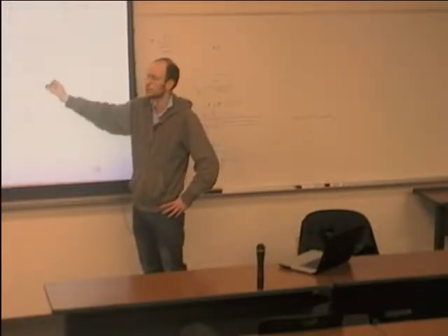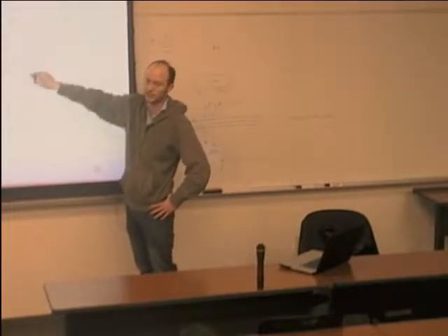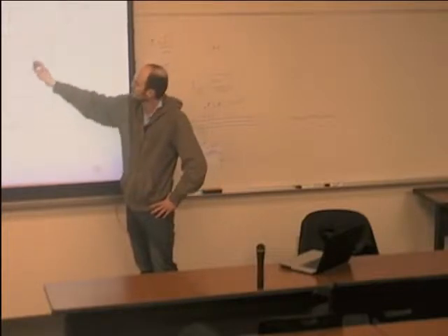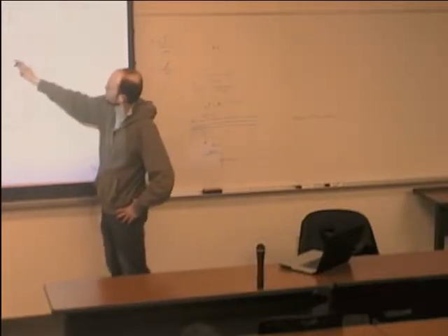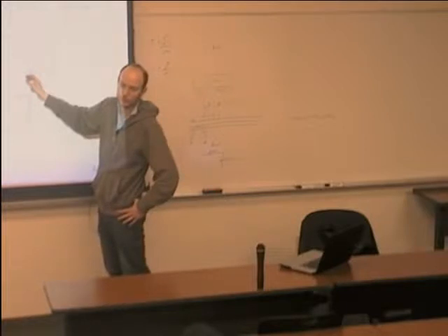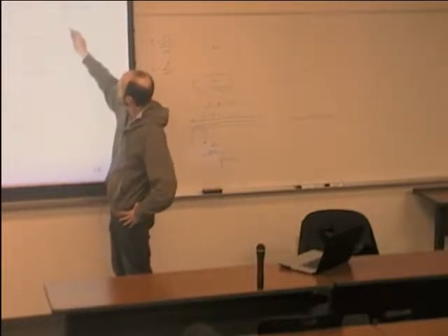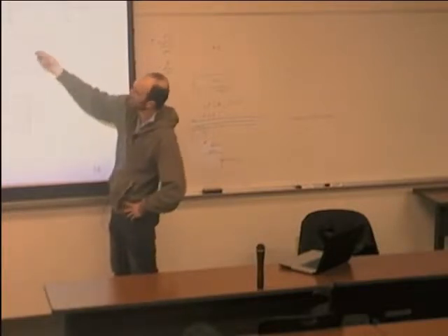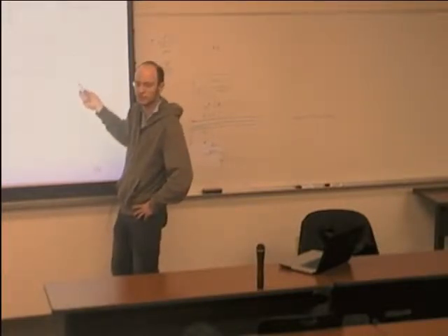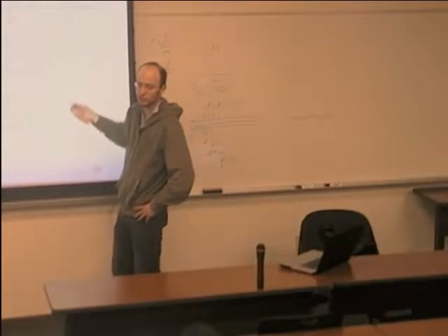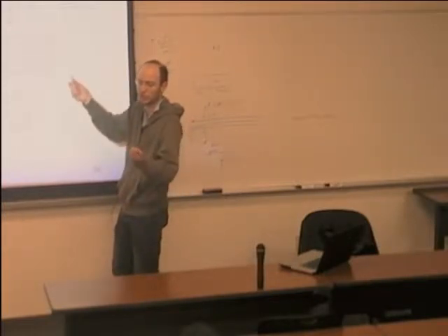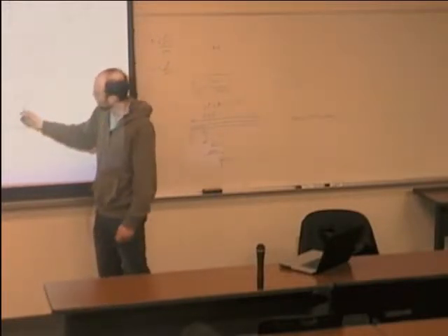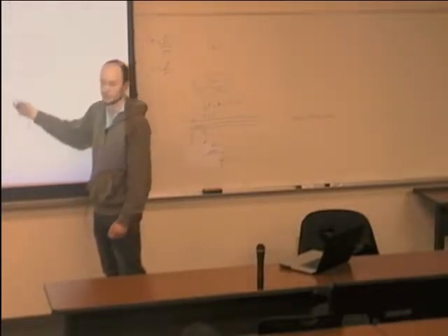We solve this exactly, and we get this equation, but it is very hard to implement, for example, in a simulator. So what you do is replace this network with some equivalent RC. How should I choose that RC? I will choose it so that I get the same propagation delay for a digital signal. So then the RC that you choose is actually this value.